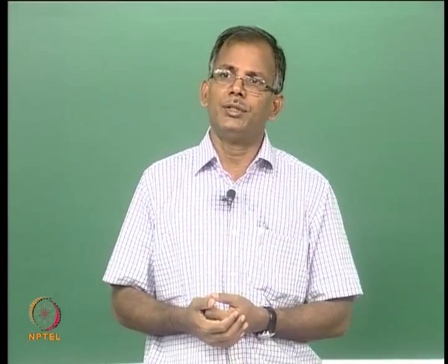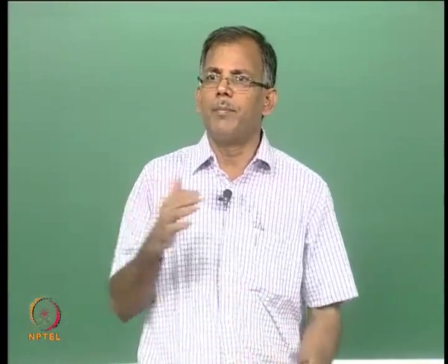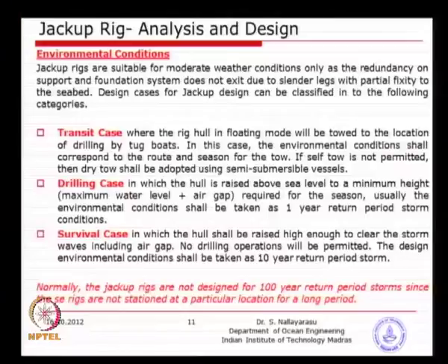That means muds can be discharged, no live loads, no crane operations. So, you have slightly reduced gravity loads, but maximum environmental loads. That is the idea behind it, and these 3 cases need to be evaluated each time a new site is selected for drilling and transit.